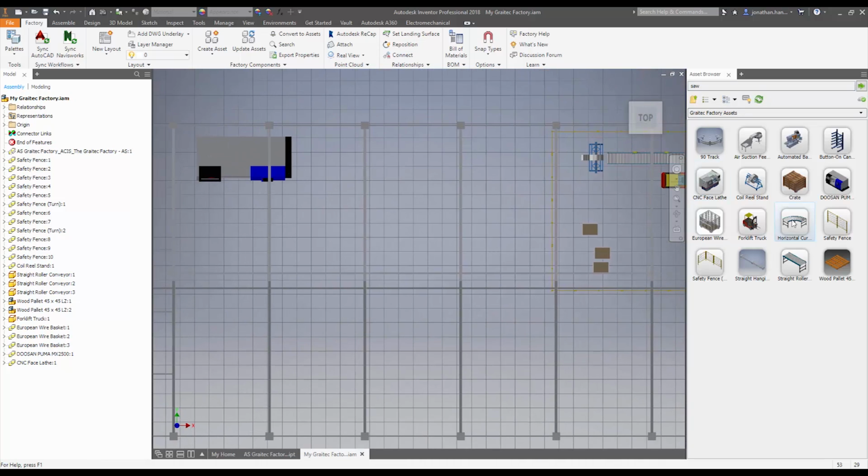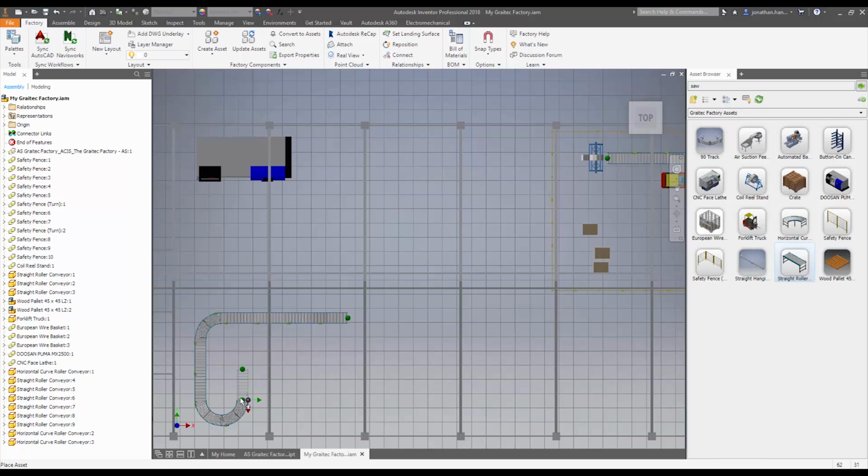So I'm going to start putting in some roller system, so position that here, and then put in some flat, and you see the way they all just tie together with them being linked elements. So you just pick your asset, drag and drop it into position.